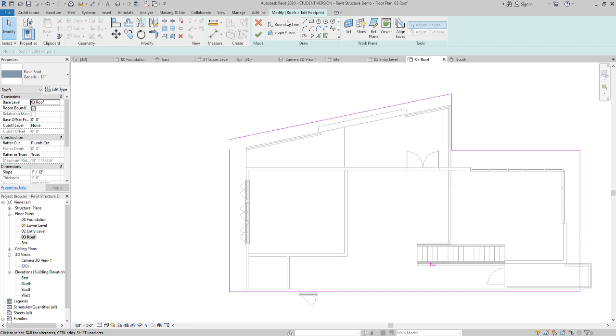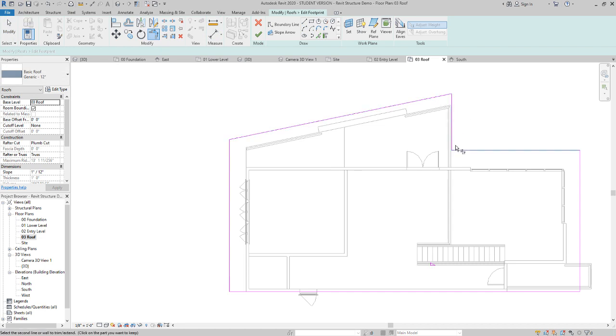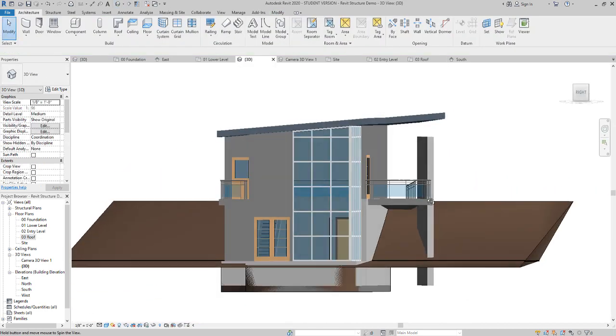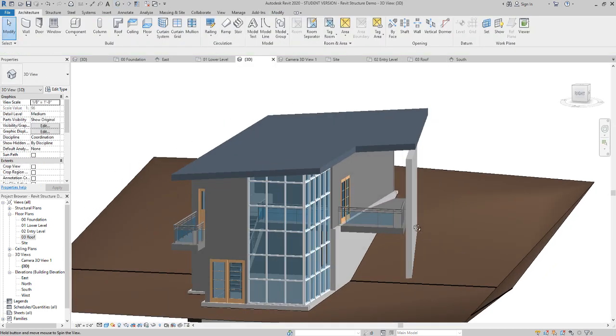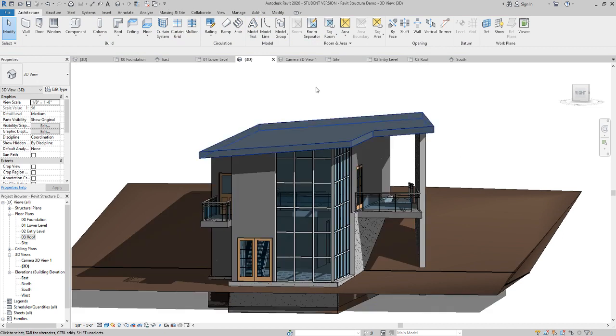As long as the sketch is good, we need to just corner that. That's cornered. This is cornered. Check that off. Go to 3D. Now we have this extension that's over. And then for the retaining wall, we click on that, attach top base, click on the roof, and now that's all the way up. Then we save this.